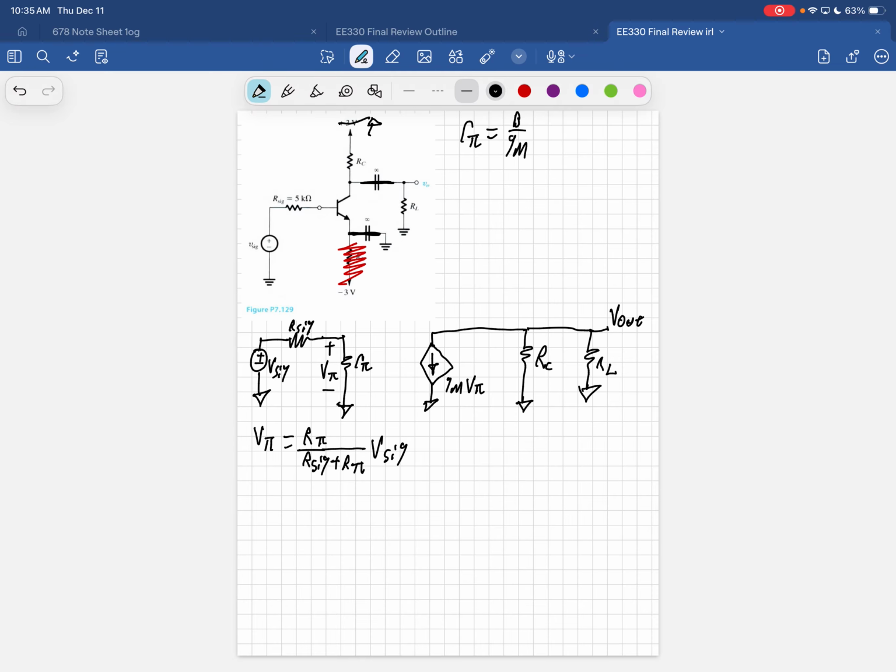So I'm going to derive the volts per volt amplification equation. Then we can find each one of the things that feeds into it, backwards. Doing the right-hand side of this, we're going to end up with a negative gain because the current source is pointing down.